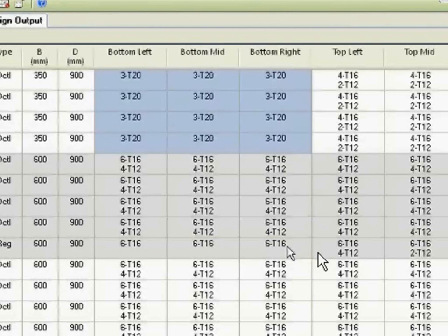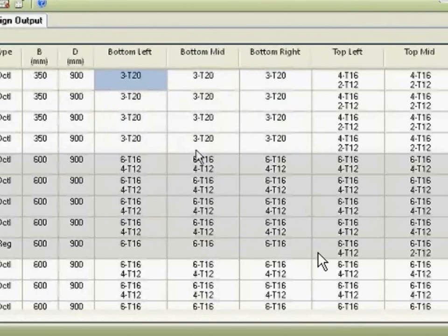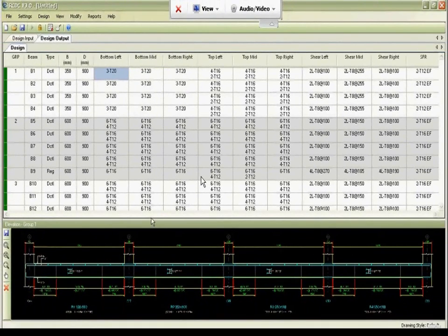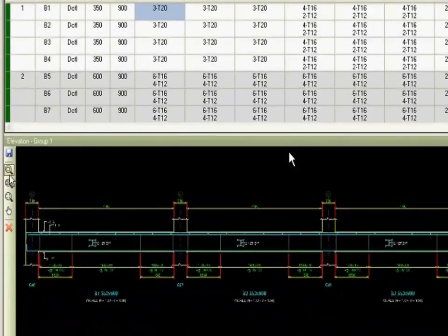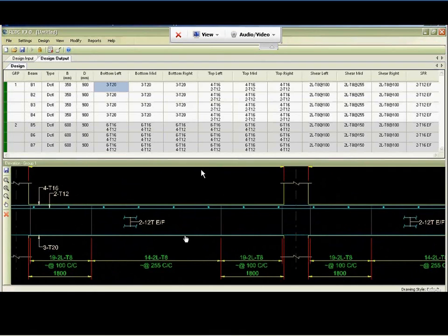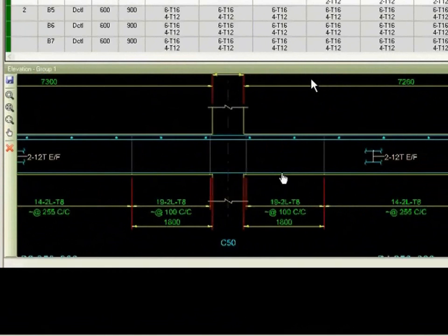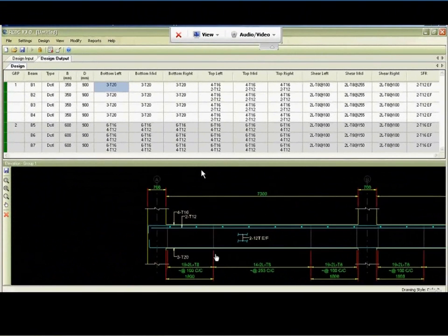One important facet that we always notice is when engineers are working with beams, you tend to work with multiple sections and the beam lengths vary. So it's very difficult for engineers without WorkX to get a feel of how the elevation actually is going to pan out once they design it. So to aid that, we have given a tool here, it's called quick elevation, wherein during the design stage itself, a proper to-scale elevation can be generated of the current detailing. So here you can see that at the bottom of the screen, it has generated the current detailing as specified by us. So the user gets a very good feel of how this detailing actually is going to pan out once it gets drawn or when it's going to get executed.